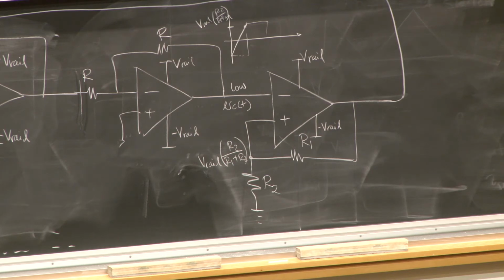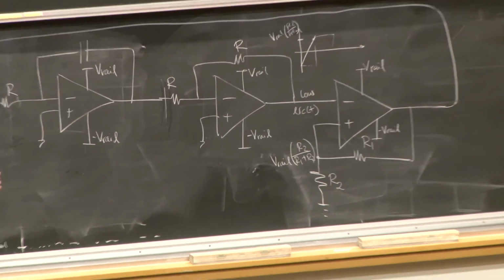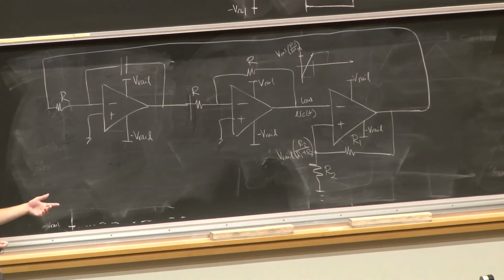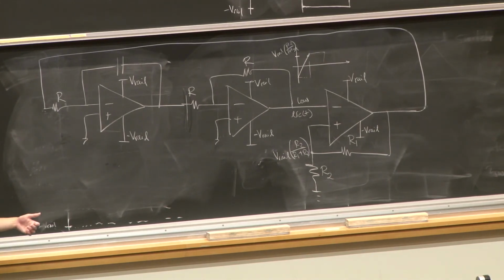So now we have it done, right? We've made a circuit that self-sustains an oscillation. Now the question is, what is the frequency of this oscillation? Does anyone know how to compute that? Yeah. It depends on how fast my capacitor is charging or discharging. That's right. So looking again only at our positive feedback circuit,